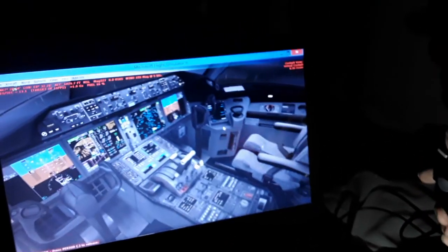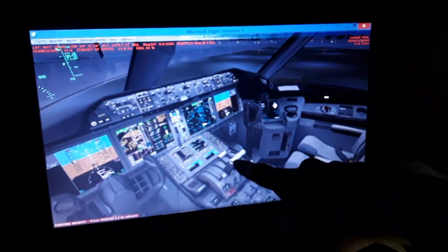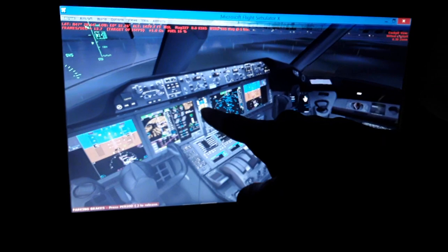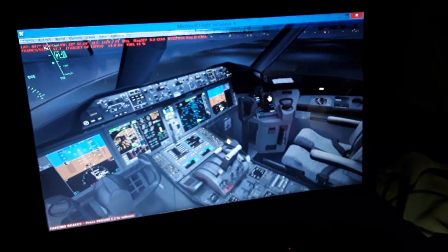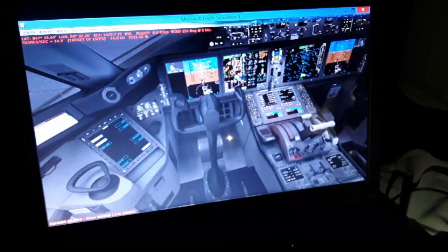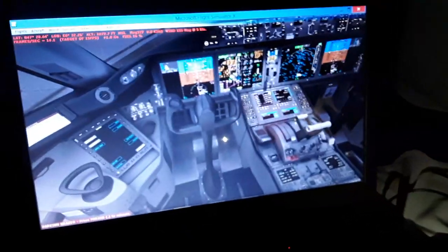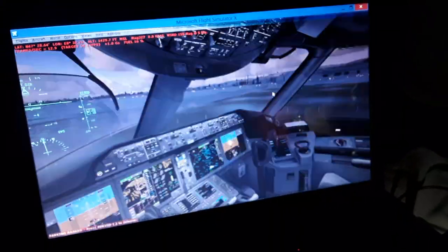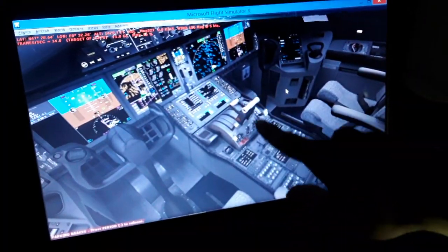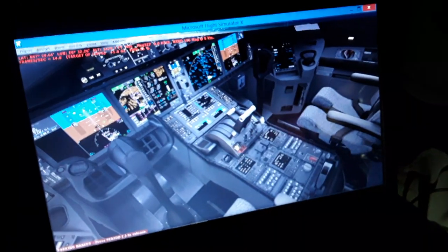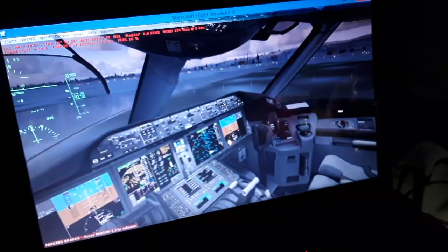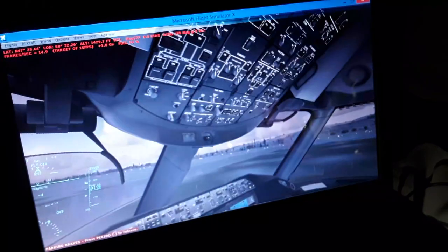To move, we have hydraulic power for the thrust reversers of the engine, for the landing gear extend and retract, parking brakes, and also normal braking, nose steering, and other functions, flaps and slats extend and retract, horizontal trim stabilizer, speed brakes. So all these use hydraulic power, which is supplied with pressure from the engines.